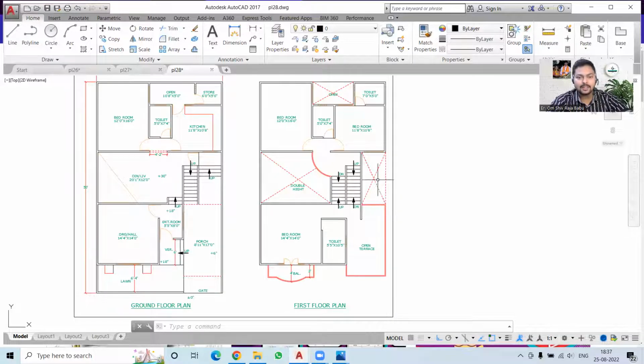Or we can also cast this over here. That is not an issue. We can also close this slab, because this is an open terrace space, so we can also use this space. And the space below the staircase can get ventilation even from this porch area, because this is quite a wide open space. If it were not that wide, then we would keep this open to provide ventilation for this kitchen. But right now I guess this is quite enough to provide the ventilation, so we can go with either this arrangement, or we can just keep it closed.